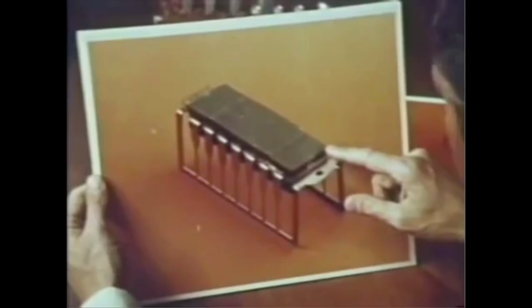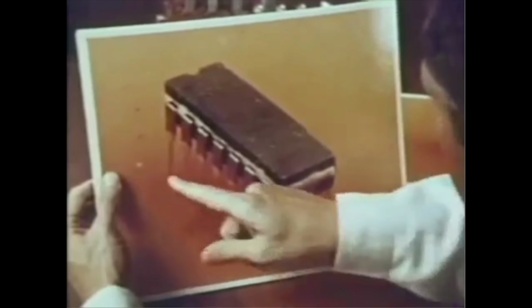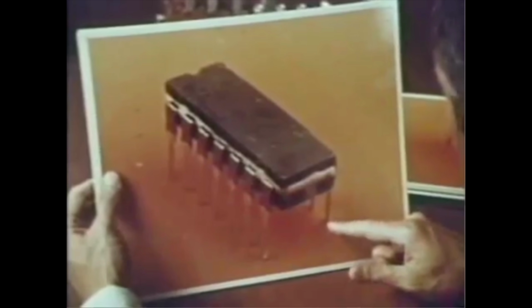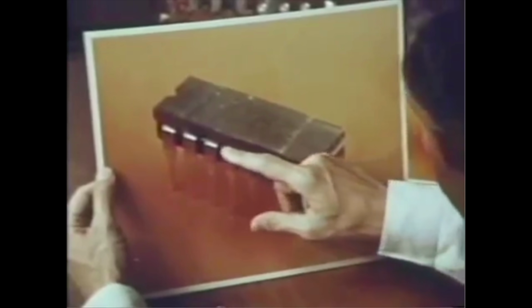The next operation will be to clip the ends of the frame. The package is now revealed in its magnificent beauty. The solder glass is peeping out, so that we have to clean that up a little bit by sending the part through the furnace along with many thousands of others, so that the solder glass is all melted in and neatly arranged in place. This is the finished dual inline package.